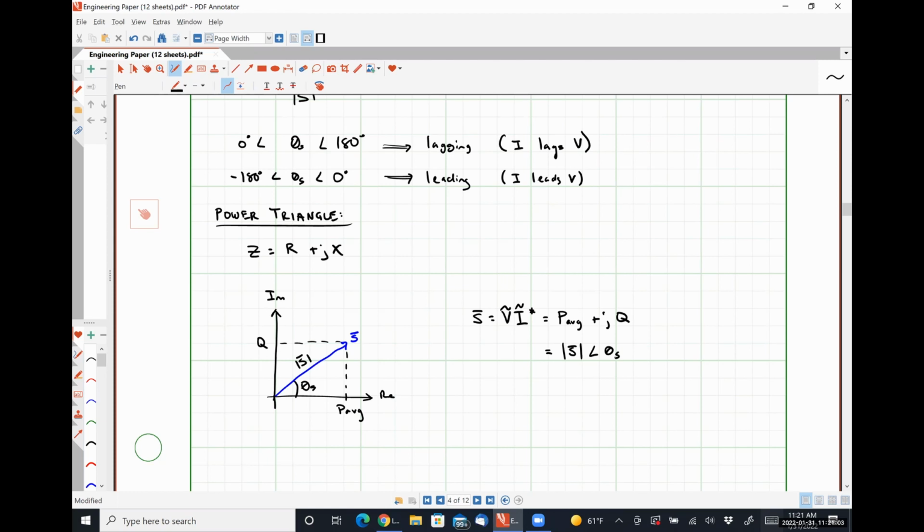So effectively, they are fining you because they are having to put infrastructure in place to deliver you a certain amount of apparent power, but you're not actually absorbing all of it, right? So that large value of power still had to be generated, which costs money, regardless of whether the load that you're connecting is capable of actually absorbing it.